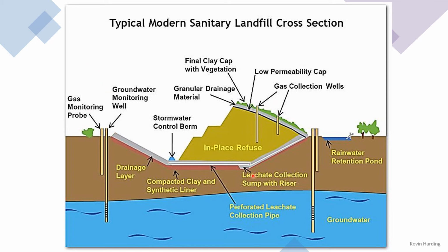If that is the case, you would not expect anything to actually collect in this leachate sump, so you would not need as big a collection point here. If you're in an area where there's a lot more rainfall than there is evaporation, so the net water onto this is greater than leaving, then this leachate will definitely collect water, and you would need to design it such that it is bigger than your zero rainfall or net zero rainfall areas.